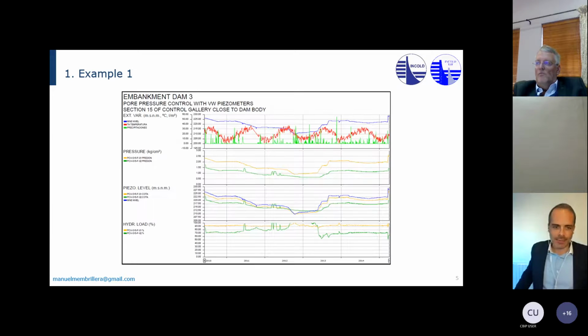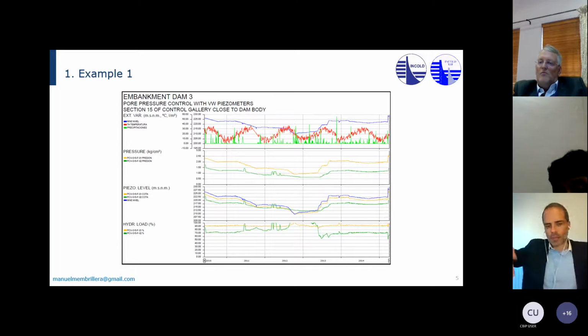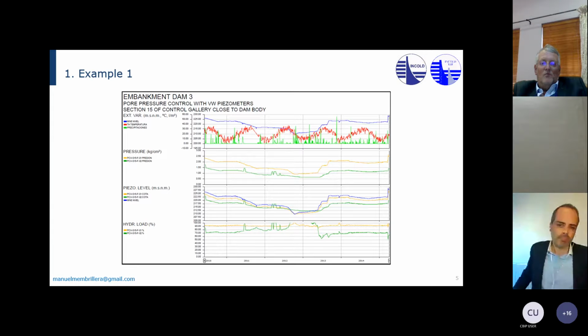So that was in the 90s, but then you can see that, well, in 2008, the dam has some drains at the toe of the dam, and we monitored the water levels in these drains, and they started to go up and down. And so that caused emergency works to do some additional grouting in the foundation, and of course we clogged and sealed those drains that were at the toe of the dam. But then, that was in 2008.